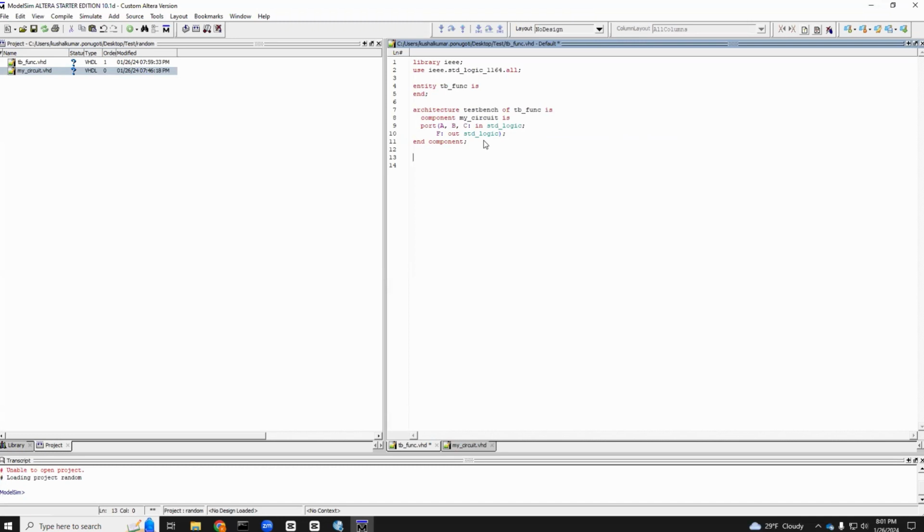Now I can declare my signals A, B, C, and F as std_logic. Then I say begin. You can write either DUT or UUT.